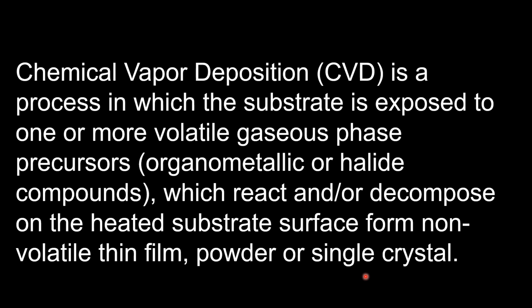That precursor material reaches the surface of the substrate, and on the surface of the substrate the precursor materials react with each other due to heat, and after reacting the precursor material gets deposited onto the surface of the substrate, where the precursor material is decomposed and converted into a solid phase thin film.